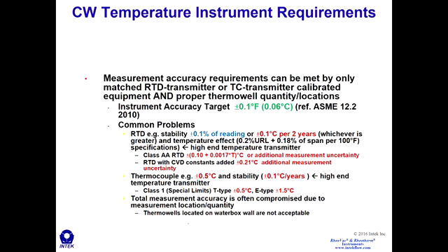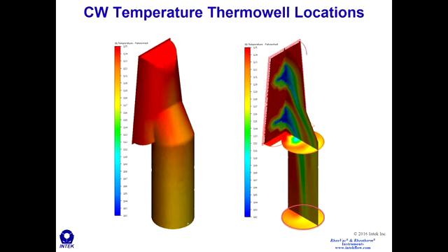So the right way to locate thermal wells for outlet temperature monitoring is to conduct a CFD analysis. It doesn't take much to do this, but you do need somebody that can provide a representative outlet tube sheet thermal stratification to start the analysis as a boundary condition.